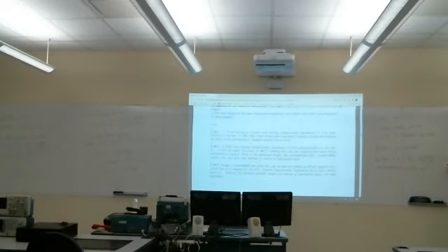So beta is 34.27 radians per meter. We multiply that by our length in meters, and we get this in radians. So it's a little past pi radians.